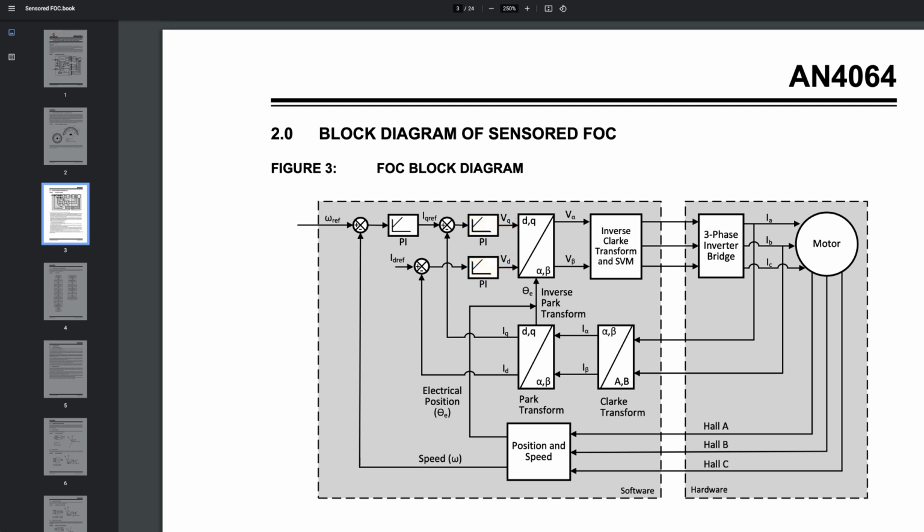Now let's look at the position feedback. In this figure, you would see there are Hall effect sensors coming in. They are feeding the phase angle information back to this loop. Now remember the voltage vectors that we talked about. Based on the angle position, it can determine where to place these voltage vectors in the loop so that it can energize the stator of the motor. It's a little complicated, I know, but as we walk through it, it will become clearer.